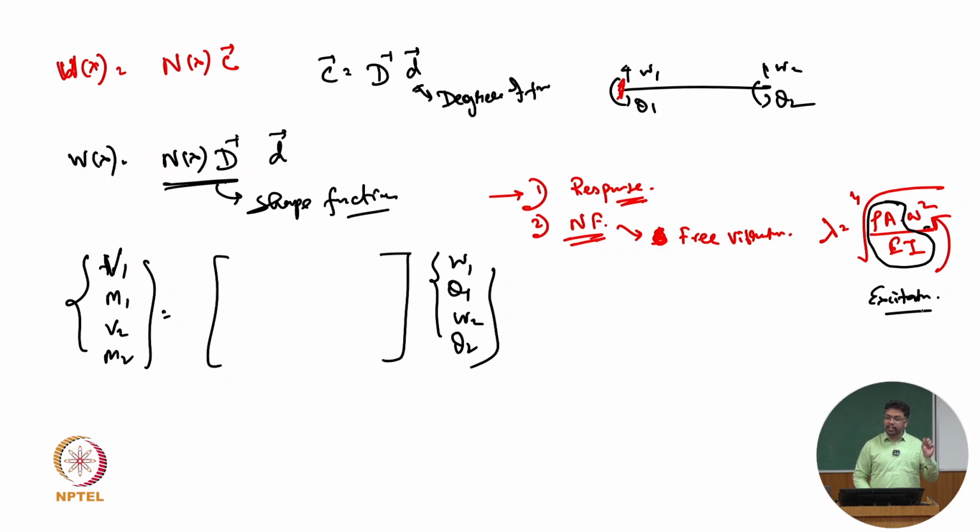Now the question comes, in case of free vibration, where is your excitation frequency? And what are we calculating in case of free vibration? Anybody try to recall? If you have a single degree of freedom system, stiffness K, mass M, free vibration, what do we try to calculate? Natural frequency, exactly. So here our target is to calculate that omega. We don't need the omega given, we will try to calculate the omega.